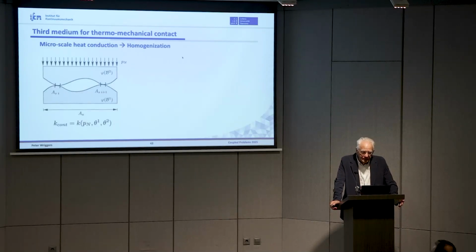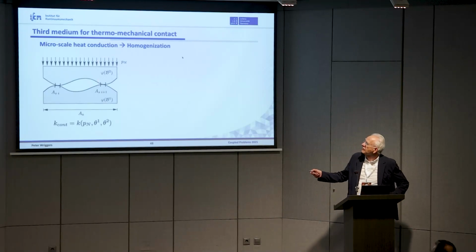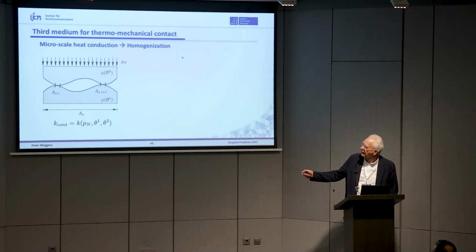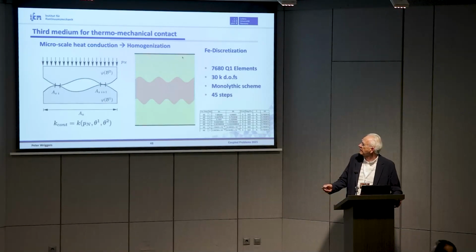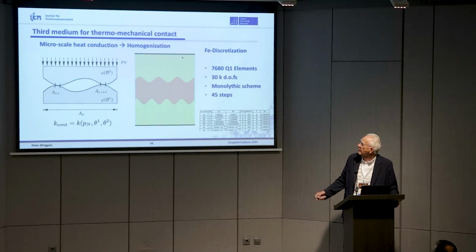Now, the other thing you could think about is homogenization. If we have microscale heat conduction, then the asperities might look like this. Then you have a spot conductance and you have the gas conductance in the interface. So classically the heat conduction here depends on the pressure and the temperatures. And I wanted to basically run this type of problem with this third media approach.